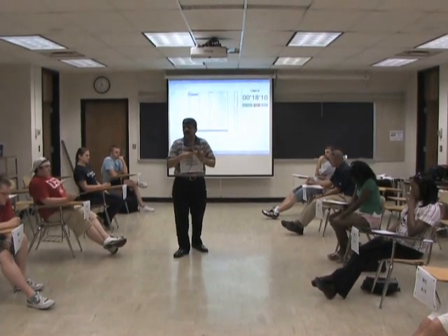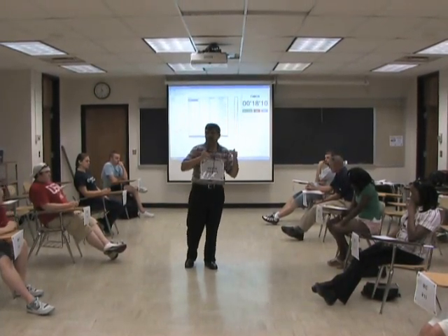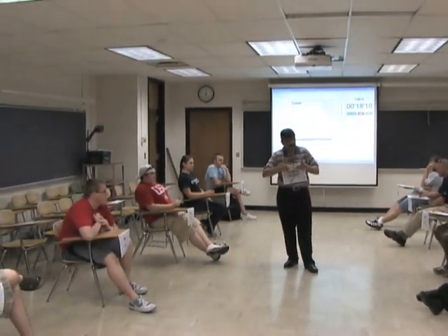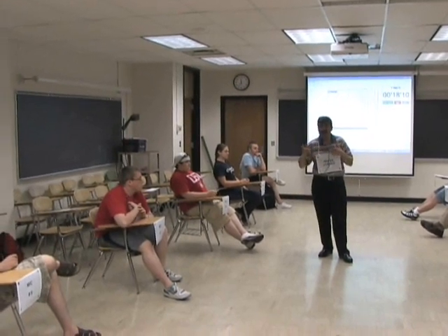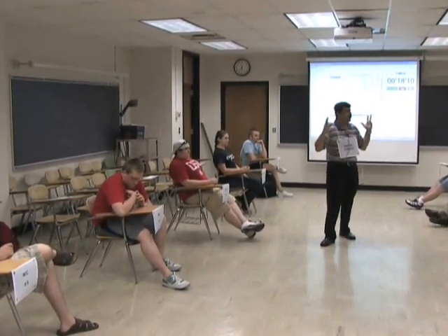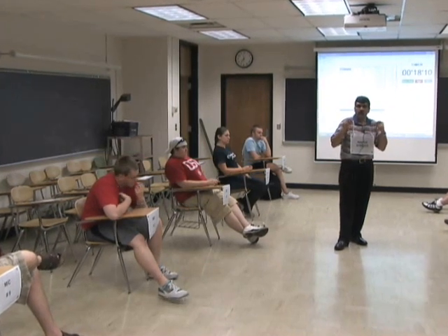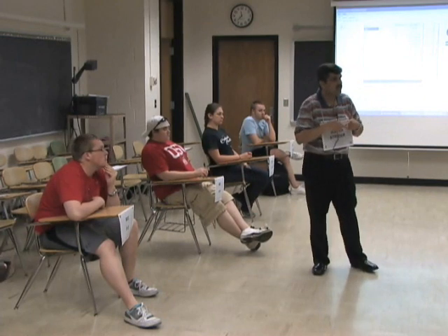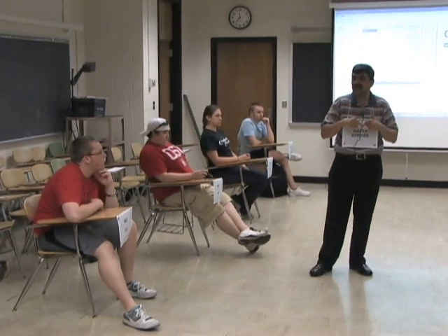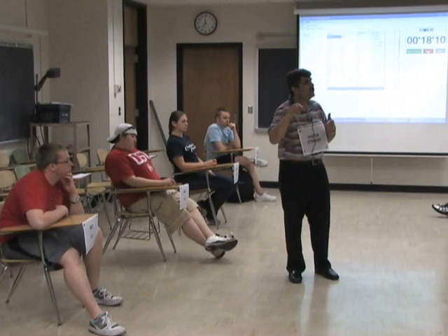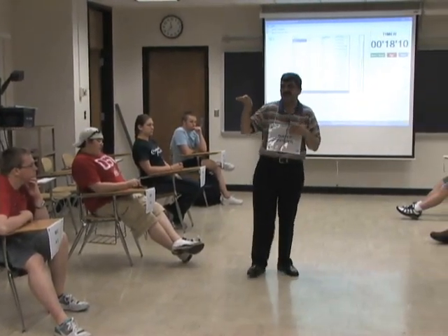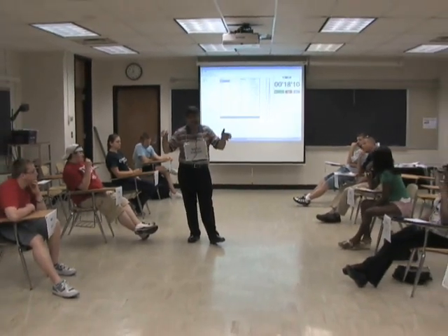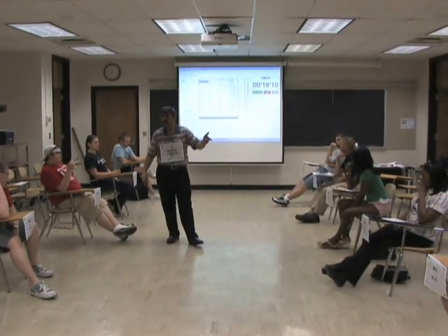Okay, and on top of that, there is high workload and low workload on the people that work on the machines that run. So equipment has differential failure rates. If we don't plan a maintenance schedule, everybody talks OEE, total productive maintenance, blah, blah, blah. One of the biggest things to look for is, what's the usage rate of the equipment? And as equipment has a higher usage rate, it's accelerating faster towards failure. It's called MTBF, mean time between failures, and MTTR is mean time to repair. So not only is there an equipment burden issue, but then there's a worker burden issue.